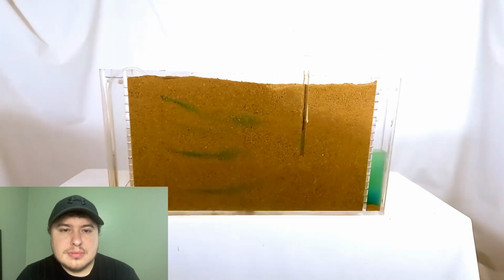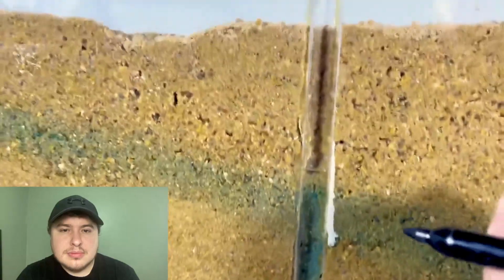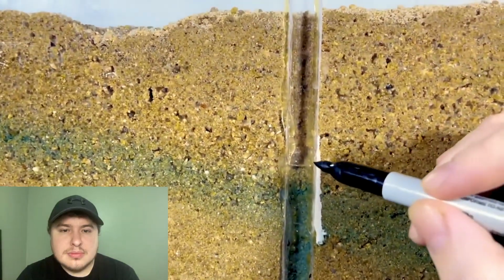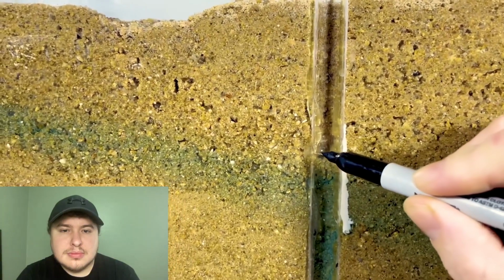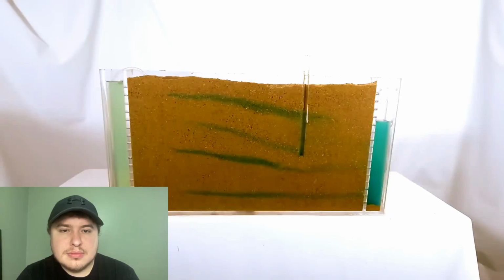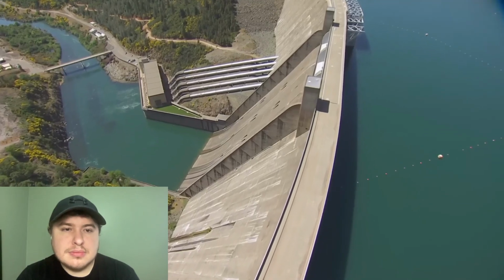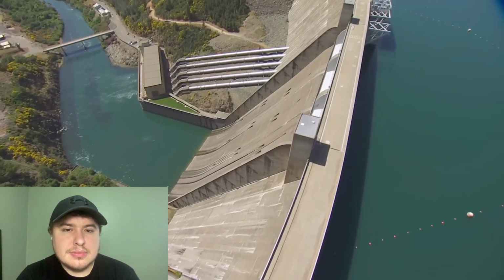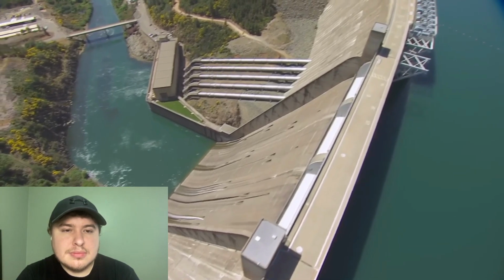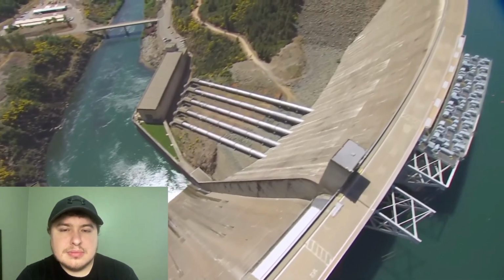But to the dismay of those early engineers, pressure from the reservoir is not the only destabilizing force on a dam. Take a look at this pipe I've included in the model that shows the water level between the two boundaries. If the base of a structure was below the water level shown here, the groundwater would be applying pressure to the bottom, counteracting its weight. We call this uplift pressure. Remember that the only reason gravity dams stay put is because of their weight. So you can see how having an unanticipated force effectively subtracting some of that weight would be a bad thing.